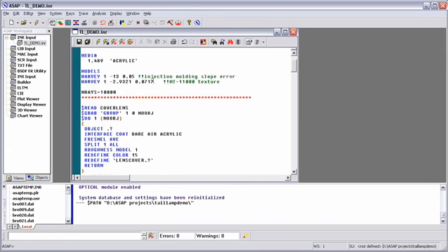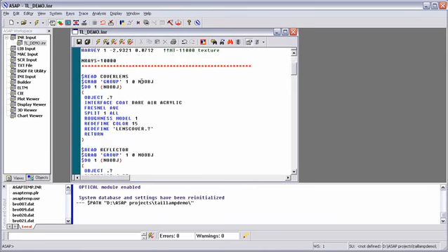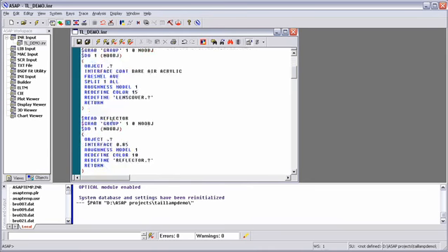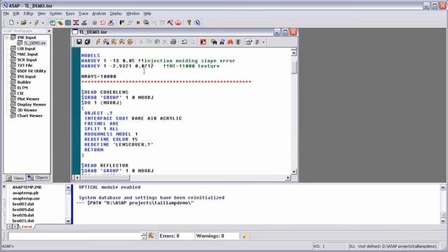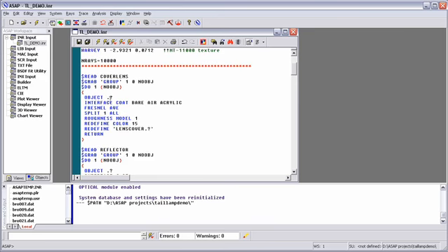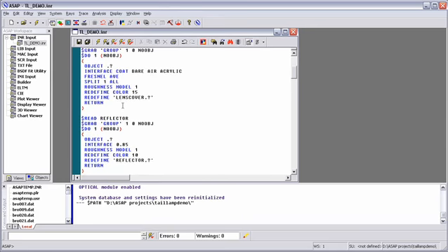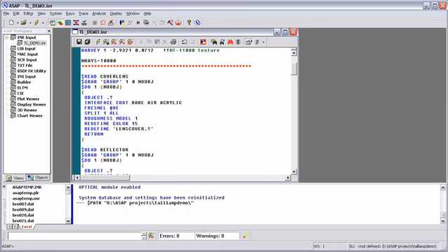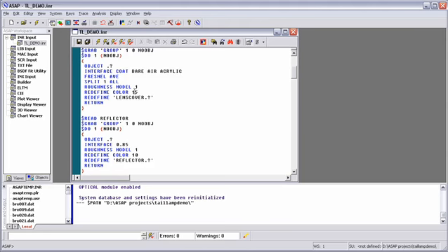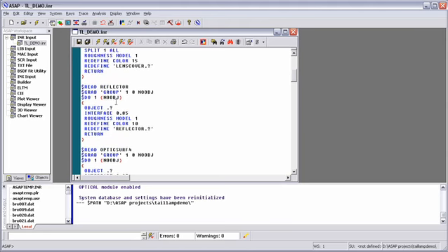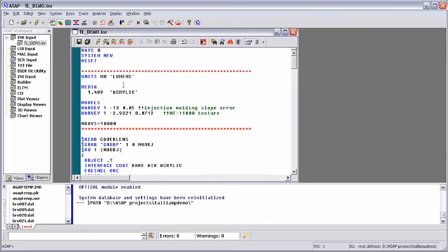I've set up my script file ahead of time to simulate the part, and we're going to simulate the cover lens, the reflector, and the optical surface that we just created. One of the things I mentioned before is that we skipped the material assignment in the IGES translator because inside my script in ASAP I can use this do-lib construct that allows me to set my material properties for each one of those components. This allows us to change material properties quickly on each one of those components, and we'll look at that a little bit later.